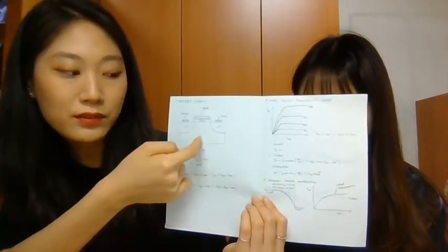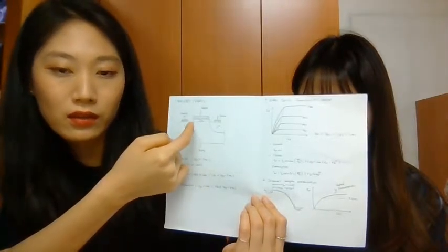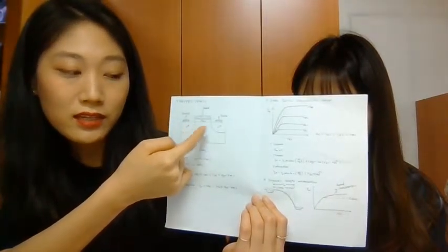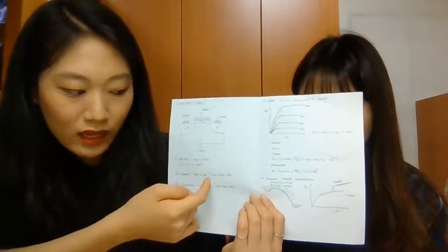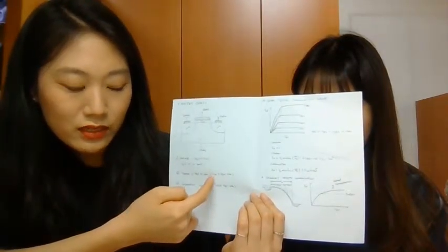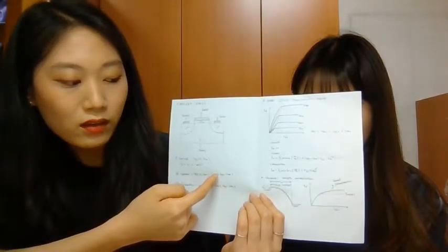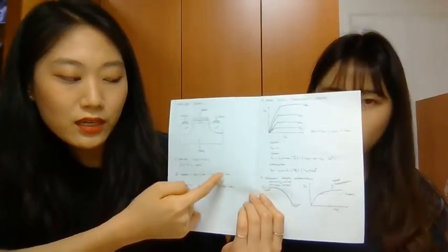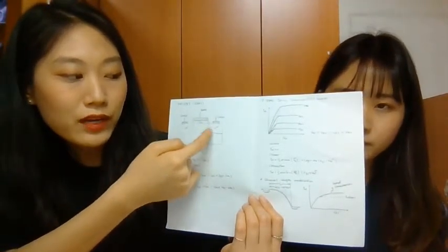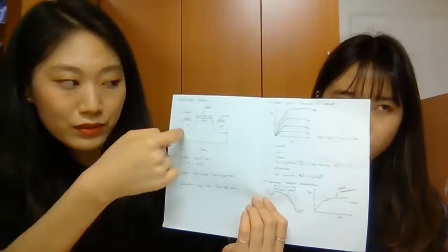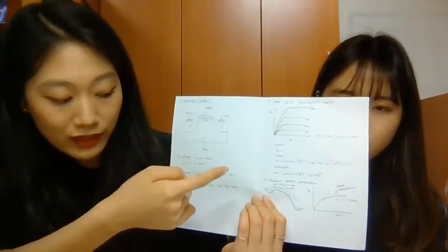Because the substrate is p-type but the channel's carrier is electron, and the drain source voltage is smaller than VGS minus VTH, the current flows from drain to source, and electrons flow from source to drain.